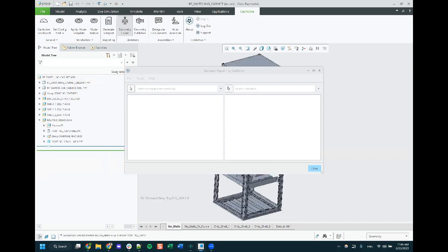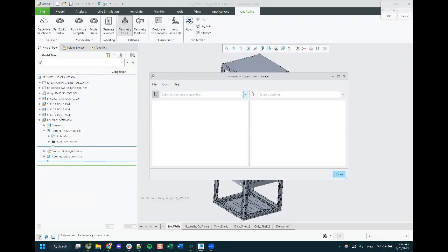What that's going to do is create a subassembly in our model with a contained skeleton and a harness part, all created inside of it. We can see that right now the skeleton is empty. It just has our starting features, three default planes and a default coordinate system. But now I can choose any level of this assembly as my equipment assembly. This is where the references are that I want to create copies of. I'm just going to middle click off in space here. When I do that, it's going to default to the top level assembly. So we should see that pop in here.